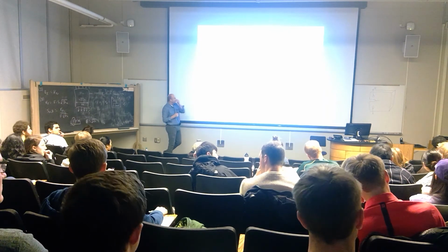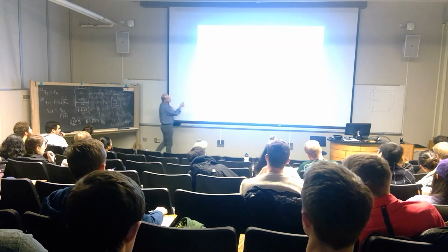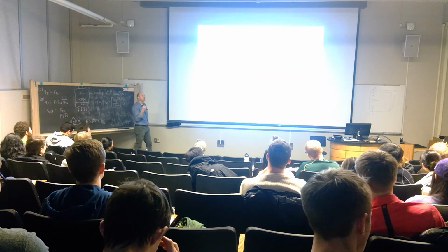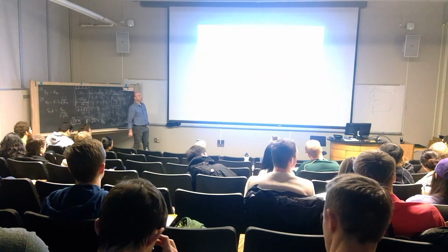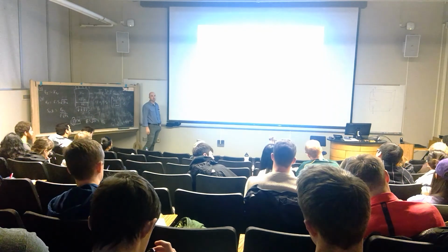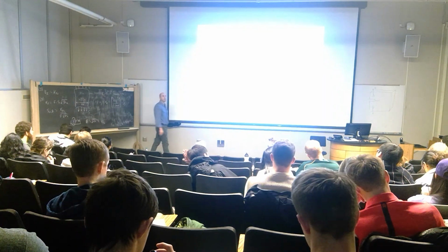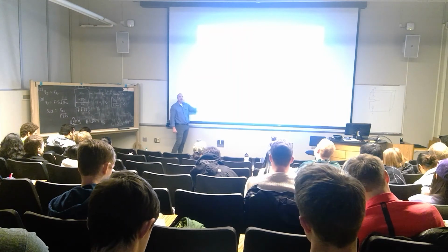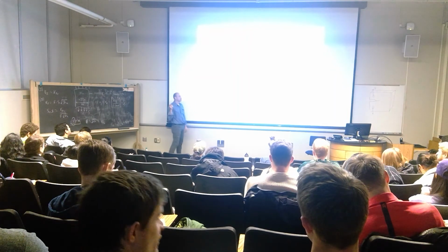So what is NDE? A sub i is either specified from something that you know, or from non-destructive inspection or non-destructive evaluation. It might be the minimum flaw length that you can see from non-destructive evaluations. Okay? So a great way to estimate what we think we can get for lives of structures.